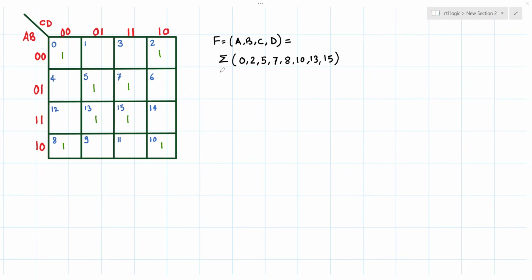So this is how all the min terms in the parentheses have been marked in the graphical representation of the K-map. Why are we doing this? Our purpose is to simplify the Boolean function or logic expression, or to simplify the logic. That's why K-maps are used as a graphical method to simplify the logic. Once we are done with that, we now have to make the grouping of the min terms. Grouping of the min terms means grouping of the ones.